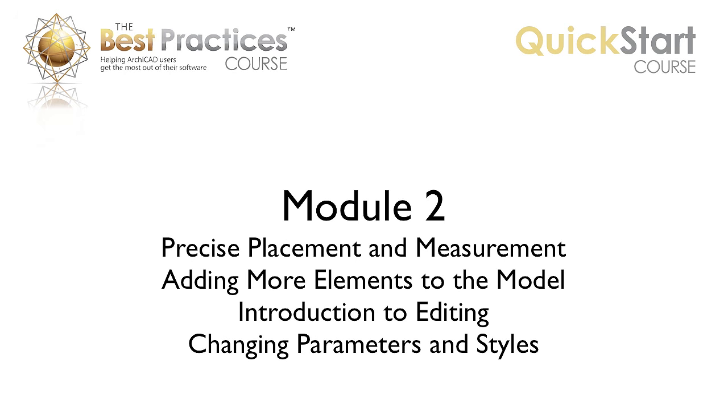In Module 2, we'll look at precise placement and measurement, how to draw things the desired length and make sure they're the right spacing and distance from each other. We'll add more elements to the model, such as columns and beams and objects, and I'll introduce you to editing, so you can select things and change them, change their parameters, perhaps the size of an element overall, or the definition of one part, perhaps the width of the door frame. We'll look at changing styles as well, such as the door panel or the material that something is made from.